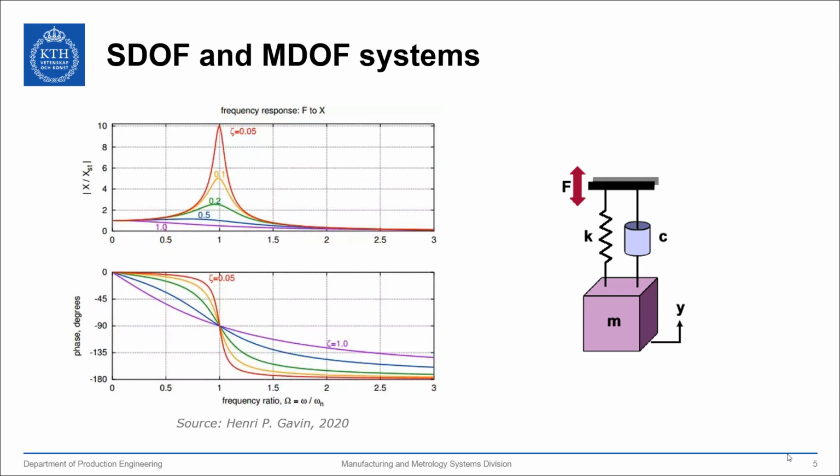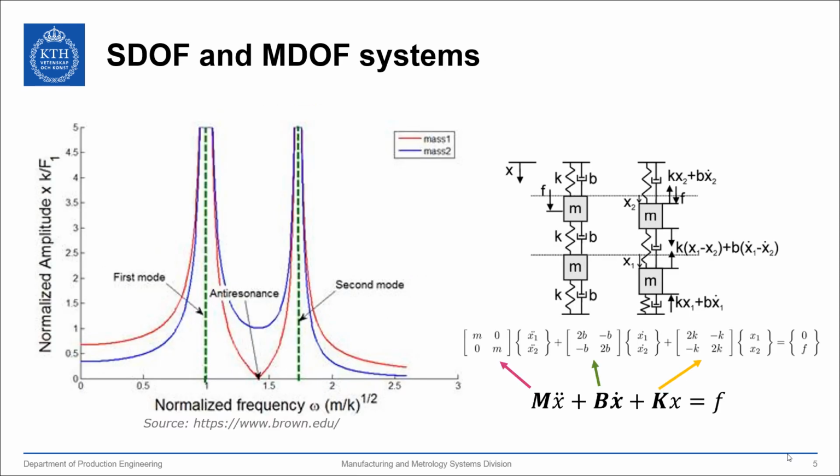In many engineering applications, the real structures are considered multiple degree of freedom systems. Thus, the dynamic problem can be reduced to an algebraic system of equations whose solution is closer to the real one for a dense discretization. As shown in the right figure, M, B, and K correspond to matrices carrying the system information of the mass, damping, and stiffness elements.